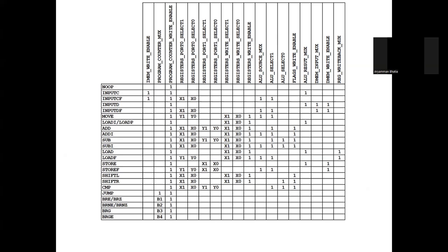So all the signals for which there's no value, you want them off in this operation. And you can notice that there are some register specific control signals, which are like the select read lines and the select write lines, which you want to have some more control over, because just by specifying which instruction you're operating, you cannot fully execute that instruction.